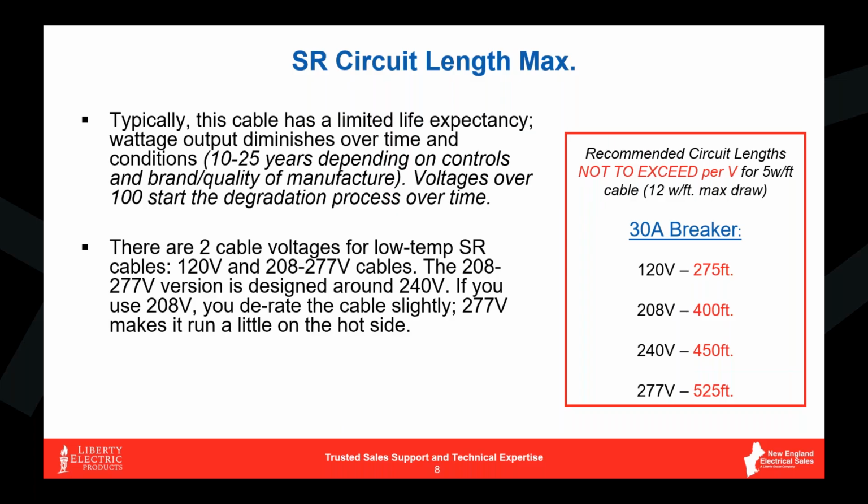The cables themselves are split into two different voltages. Generally, and again, there are some niche applications where we can get into higher voltages on cables, but 99.5, 99.9% of this market is going to operate between a 120 volt version of a heating cable, and the other version, which will be able to handle 208 through 277. But the cable is designed around 240 volt, okay?